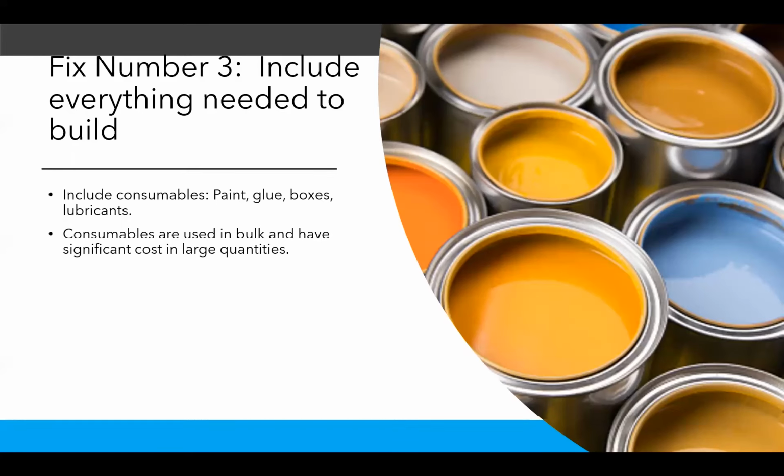Right? So including them on the bill of material also reduces the risk of missing them in the build phase. What I mean by that is, if they're on the bill of material in the ERP, and they're in the shop orders for the guys on the floor, then they will be more likely to remember that those pieces get added, that you're not going to miss them, right? So it's really important that you have all the possible things, even consumables. Just because they're not a designed part doesn't mean they shouldn't be on the manufacturing bill of material.